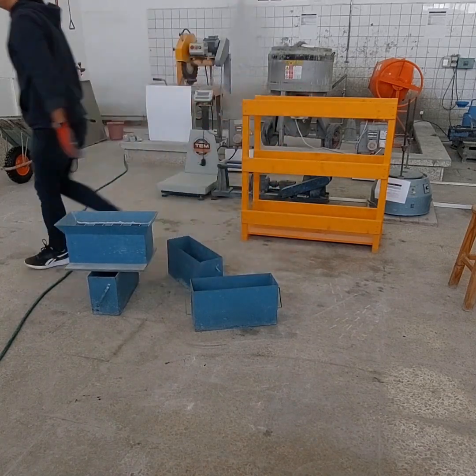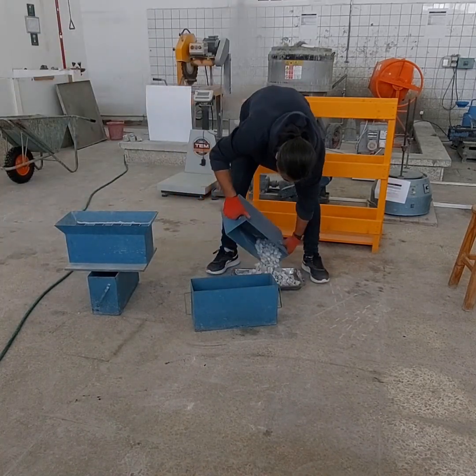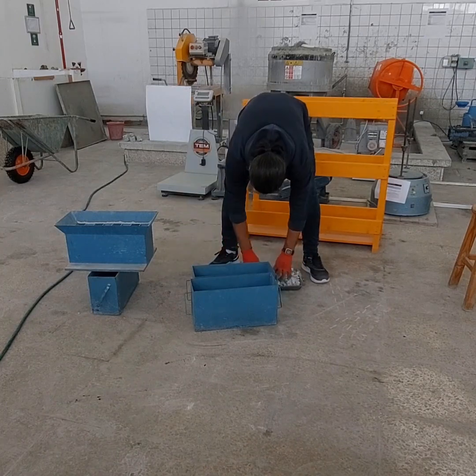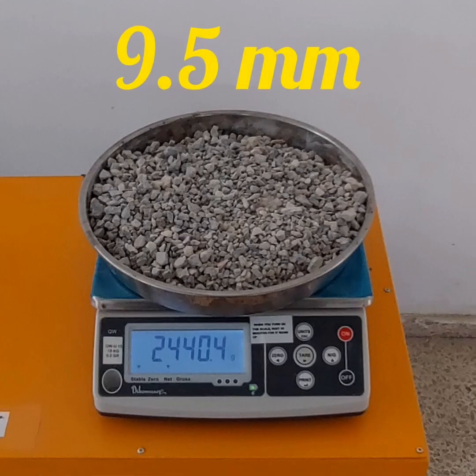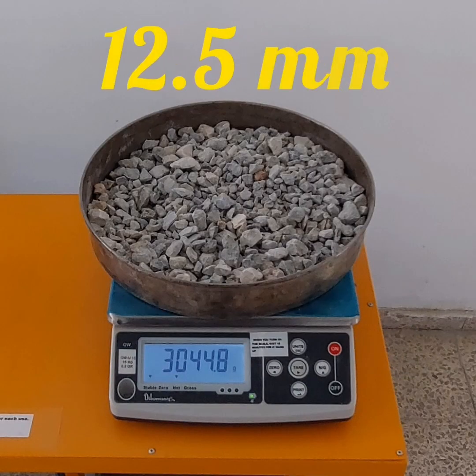Once the samples have been prepared, we need to place them in an oven at a temperature of 110 plus or minus 5 degrees Celsius for 24 hours to meet the standard requirements. After that, we remove the samples from the oven and weigh them to ensure that we have the desired amount for testing.